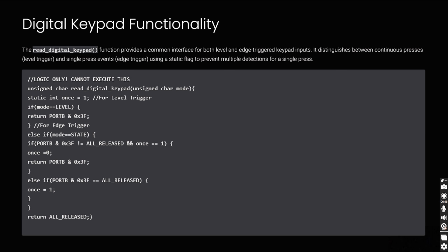For the switches to be input, we assign the value 1. But RB6 and RB7 cannot be assigned values as input or output. Therefore, retain the same value x that it exists in, where x can be 0 or 1. For this, we use the bitwise OR operator given as TRISB equal to TRISB bitwise OR 0x3F.